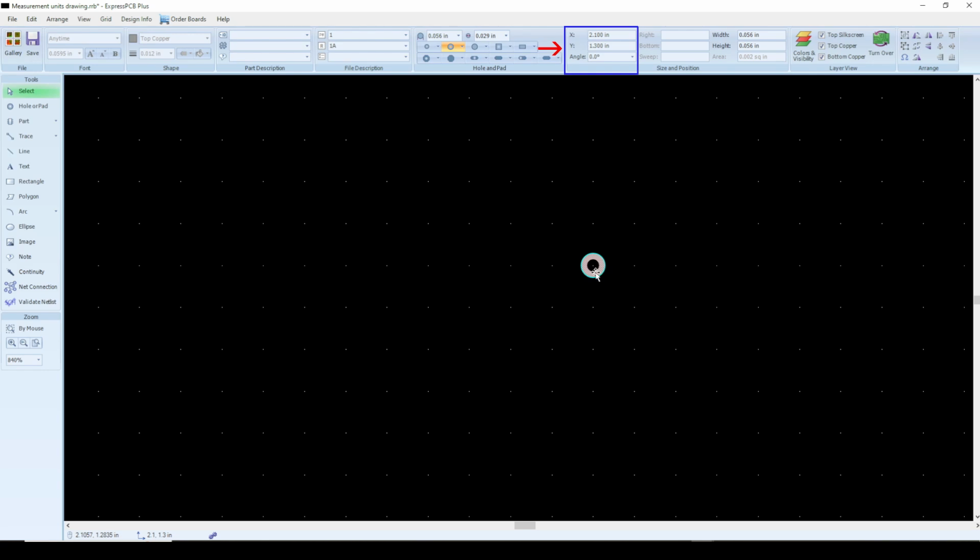Now, when I'm dragging like that, it snaps easily. And when I release it, it's going to stay at the last point that it snapped to. Now, I can snap in any direction. I can snap it this way or down, left or right. And it's always going to jump 2 because of our snap value setting.